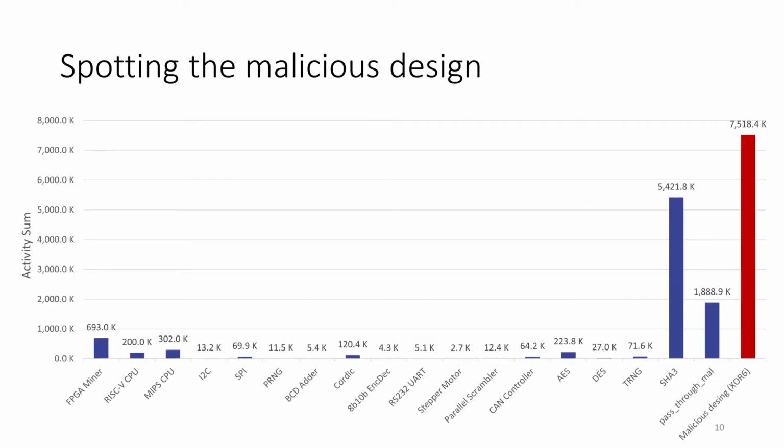We did scan many different benchmark designs and the malicious design with the new signature scan. From the graph, you can clearly see that the malicious design stands out. Our particular SHA-3 design stands out as well, because it uses a lot of wide XOR functions and bit shuffling operations in an unrolled fashion, which can potentially cause a lot of glitches. It is important to keep in mind though that our model isn't quite accurate yet, because we assume that all of the inputs change at every rising clock edge, and that the glitches always propagate through the entire combinatorial path without any cancelling out effects.